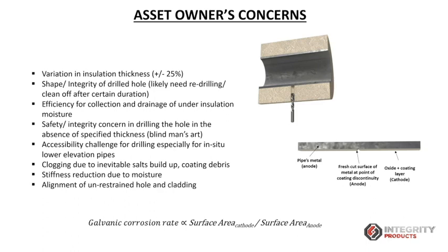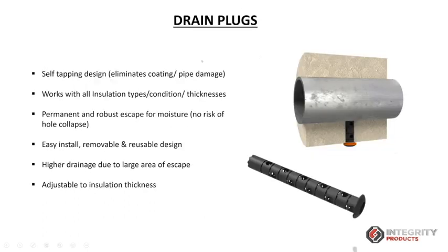And also the concern is that due to pipe vibrations or due to thermal expansion of the stone wool insulation, the hole in the jacketing can get misaligned from the hole in the insulation. So once these get misaligned, again, this hole would be clogged. So here is the thing, what is the benefit?